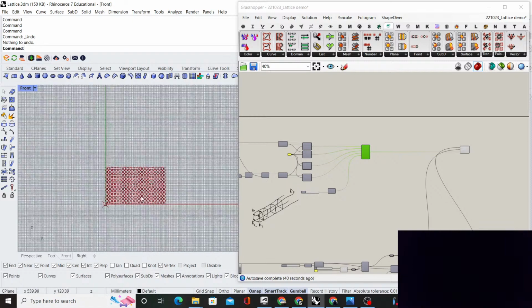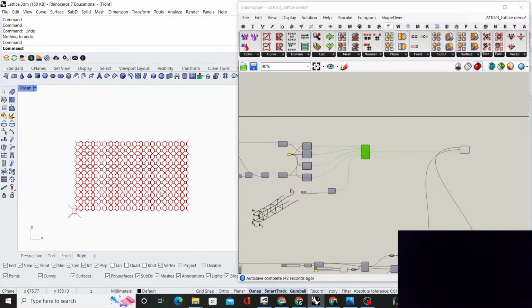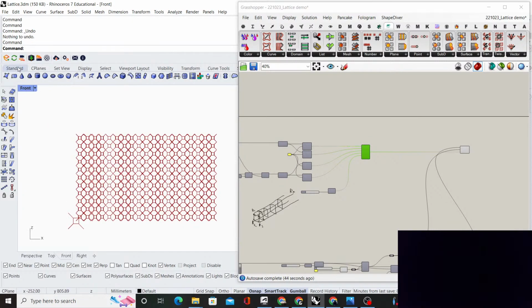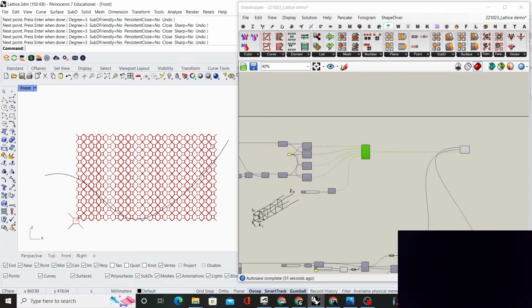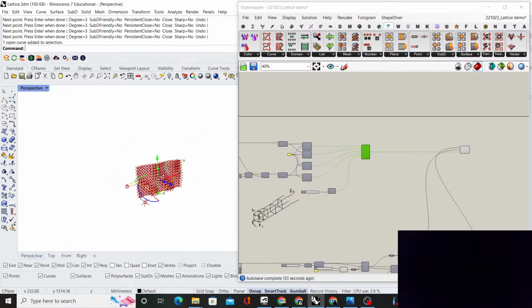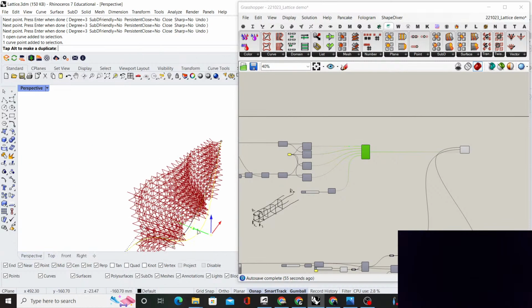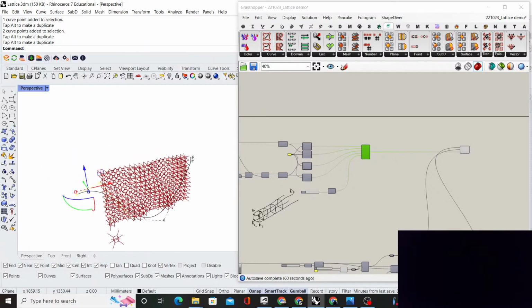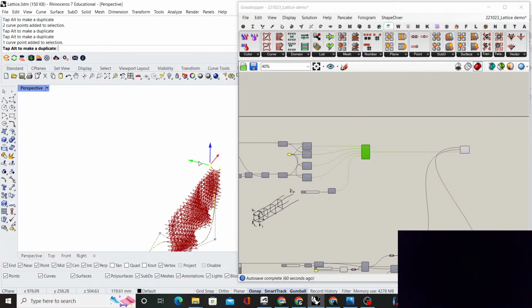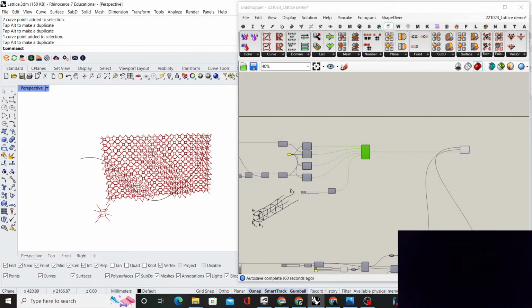So let's go to front, and let's switch off the grid because it's quite annoying, and let's draw a curve as an attractor. Yeah, I'm gonna draw this curve. I'm gonna go to perspective, move its points a little bit. Again, also different from all other tutorials. It's not. But now I'm going to show you something which I personally find quite useful and quite interesting.